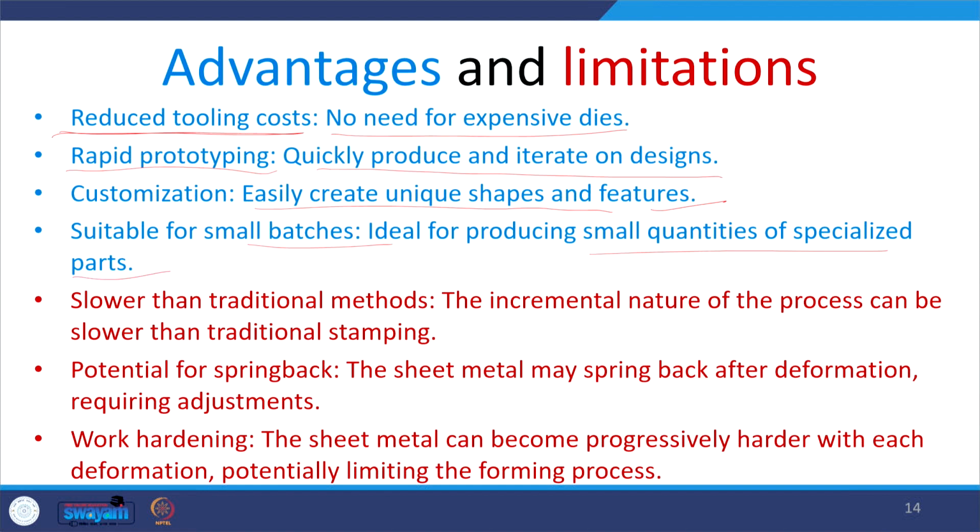As far as the limitations are concerned, the process is slower than the traditional method because the desired shape in the traditional method is realized in one go, while in incremental forming it will be done in a number of steps and it will be time consuming. So, the incremental nature of the process can be slower than traditional stamping, and there is a potential for spring back.